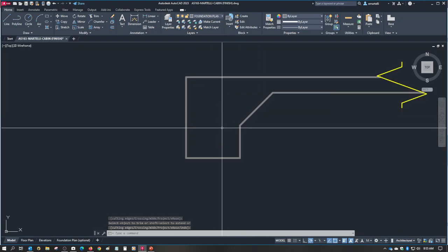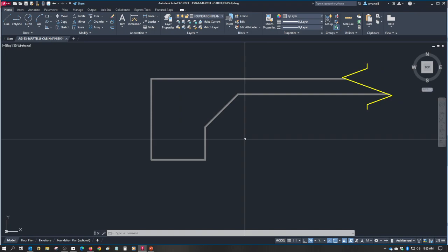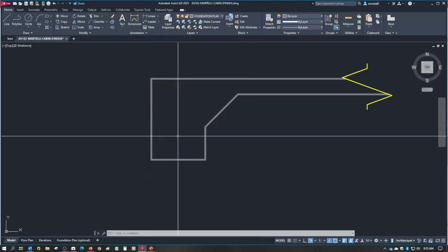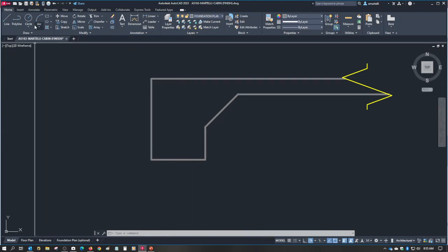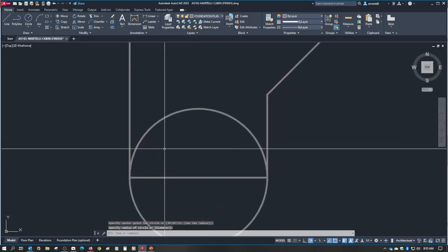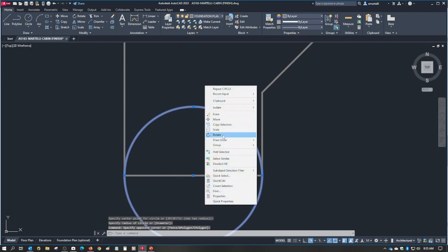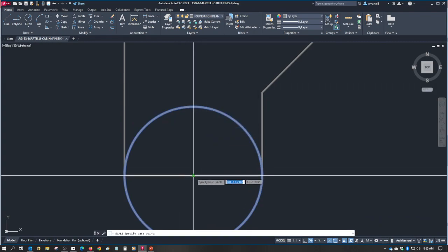There is rebar in it, and nowhere in the book do they describe that. But generally that rebar is going to be 1/3 of the way from the bottom, and you're going to get 2 pieces, one at 1/3 and one at 2/3 across the span of your footer. So I'm going to pick circle and just draw a circle out like this. They don't specify the rebar size either, but I'll tell you right now. I'm going to scale this circle from its center 1/3.